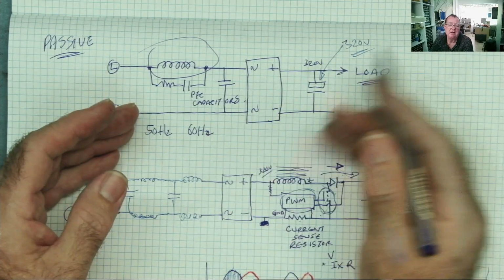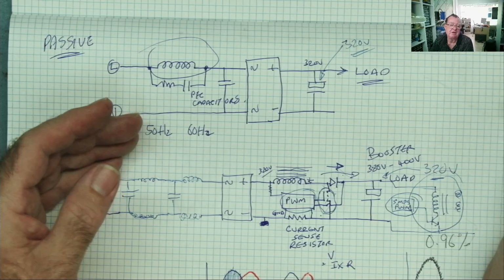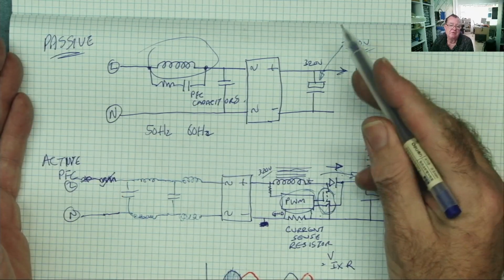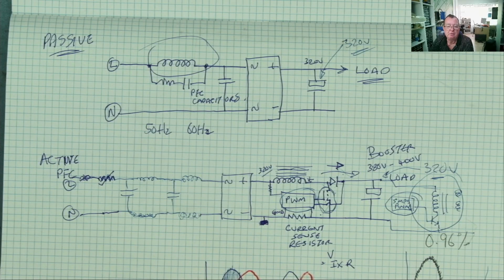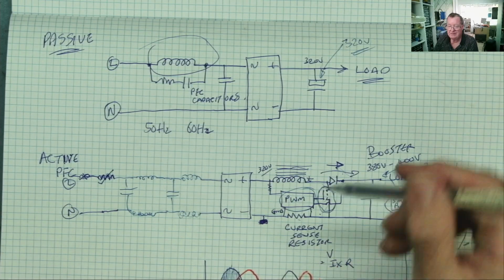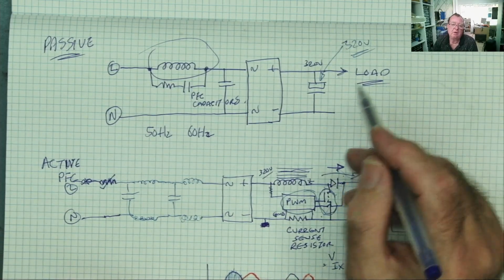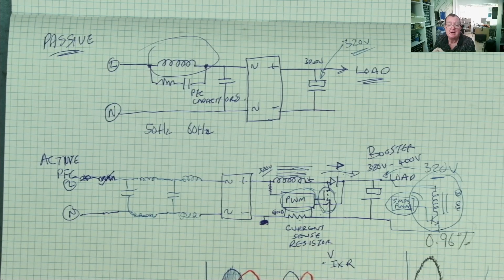You've plugged the mains in, it doesn't come on, nothing appears to happen. You disconnect the mains, you've got a nasty 320 volts in those 1 or 2 large capacitors waiting quite happily for your finger to come along, and then you'll find out. So a lot of us know this. If you didn't, you know this now.